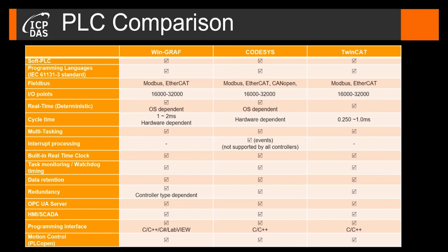So the number of I/O points supported by soft PLCs is almost unlimited, while the number of I/O points of hard PLCs is limited by hardware and local I/O expansion boards. Soft PLCs, compared to hard PLCs, also have the ability to manage and store large amounts of data because the PC memory size is considerably larger than that of a hard PLC.